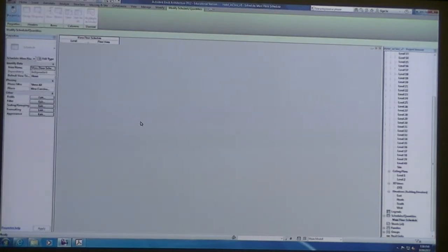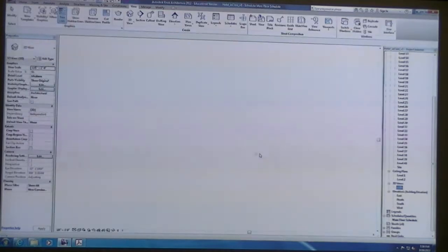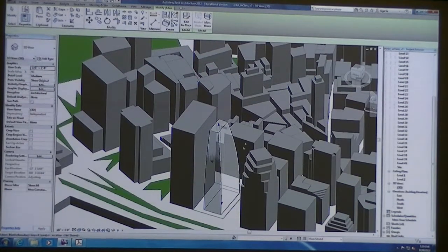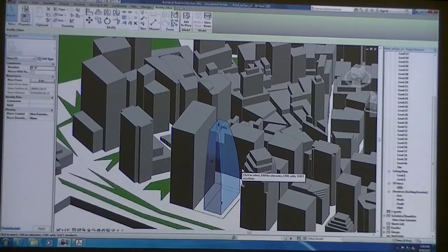So when you build a new mass, that's going to be your massing of your hotel, and you add floor masses to each of the levels, you should be able to check your square footage to make sure that you're, one, inside this mass. This is your zoning mass. You can't poke outside of this. And you're within 287,000 square feet.